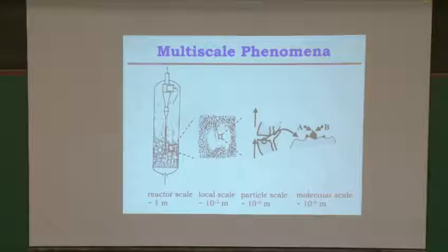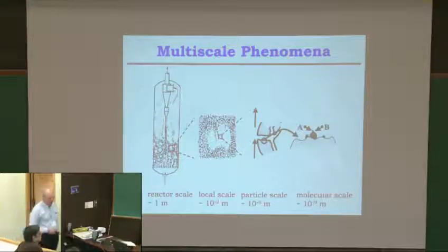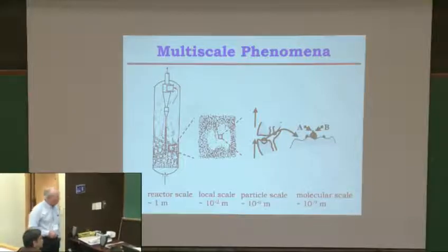Okay, so of course we know in fluid beds, as in all multiphase reactors, there's multiscale phenomena involved. We start on a molecular scale. One of the critical aspects, of course, is to have a kinetic model. And in my experience, most industrial processes don't. There are kinetic models of empirical types, but typically understanding the phenomena on a molecular scale is often done in an empirical fashion. There's not too many processes I know of where we have detailed kinetic models that can describe how reactants become transformed.